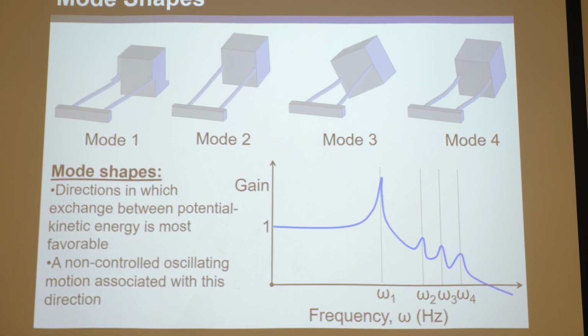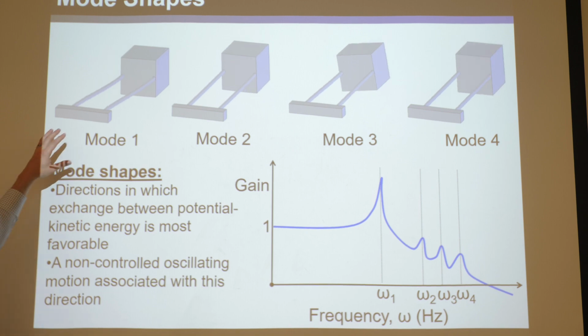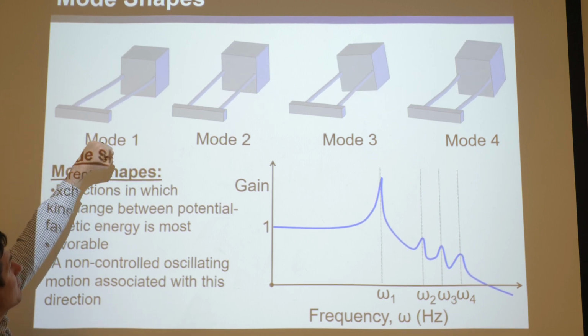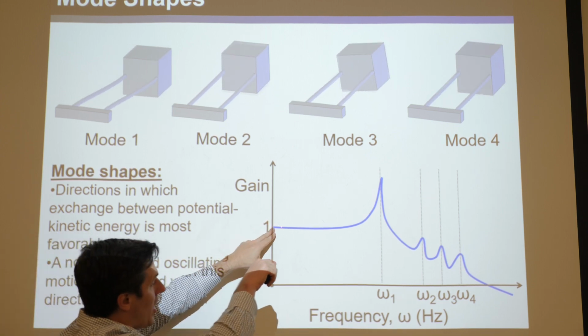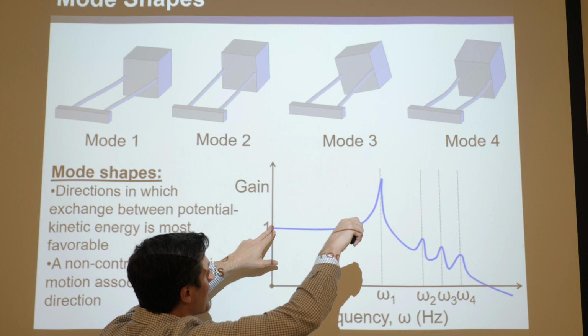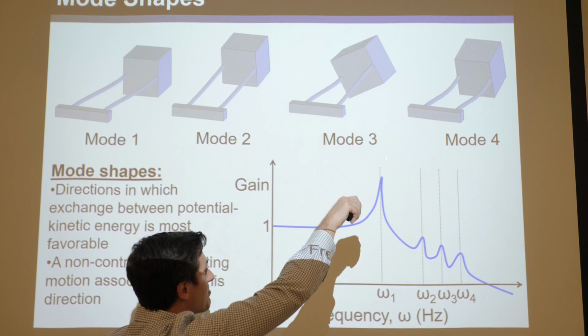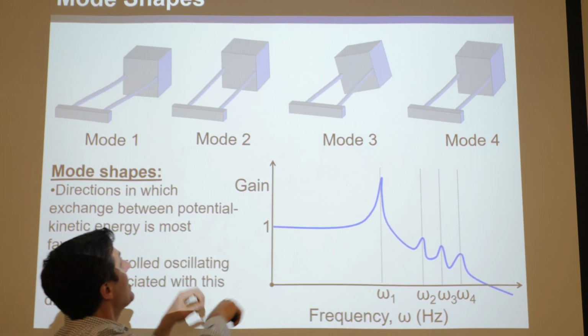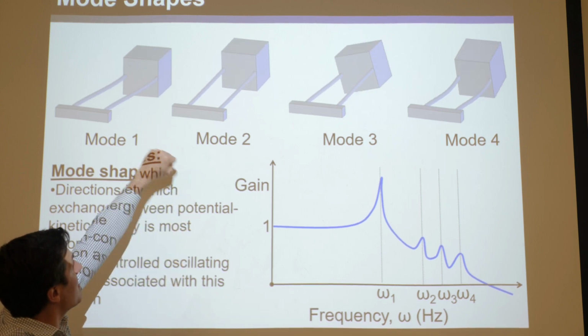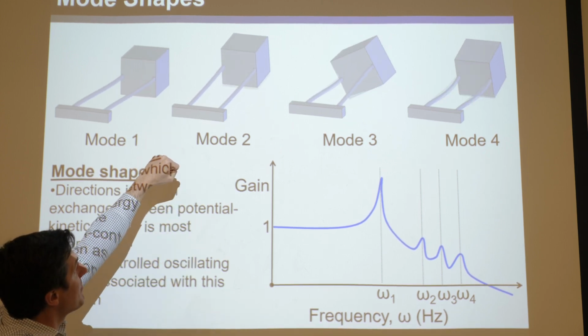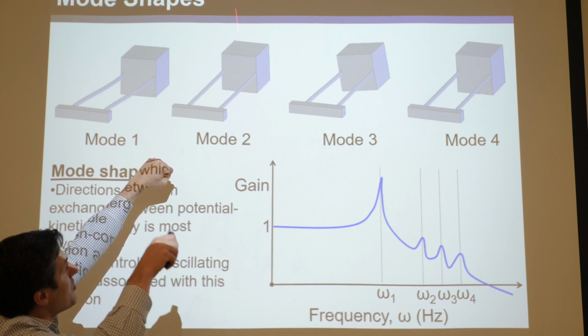So the way this works is, imagine I grab this end and I start loading it back and forth in the direction of the first natural frequency. Well, what'll happen is, you'll get a gain of 1, as usual, and then when you hit that first natural frequency, it'll freak out with a huge spike, and then it'll go down. Now you'd think, well, hold on, if I still keep oscillating in the direction of the first natural frequency, how could the second mode shape be excited?